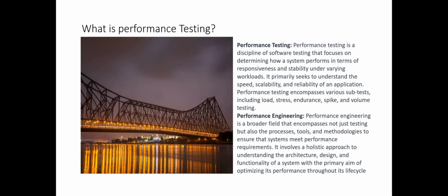Before they hand it over, they need to do some assessment on the bridge. They need to understand how much load the bridge can handle, how many trucks, buses, or vehicles it can carry, and how many users. If there is a big crowd, how much weight can it handle? They do this assessment maybe using mock or dummy trucks or dummy weight, keeping it on the bridge to see if it can handle that load. Only after that complete assessment is done will they release it for public usage.